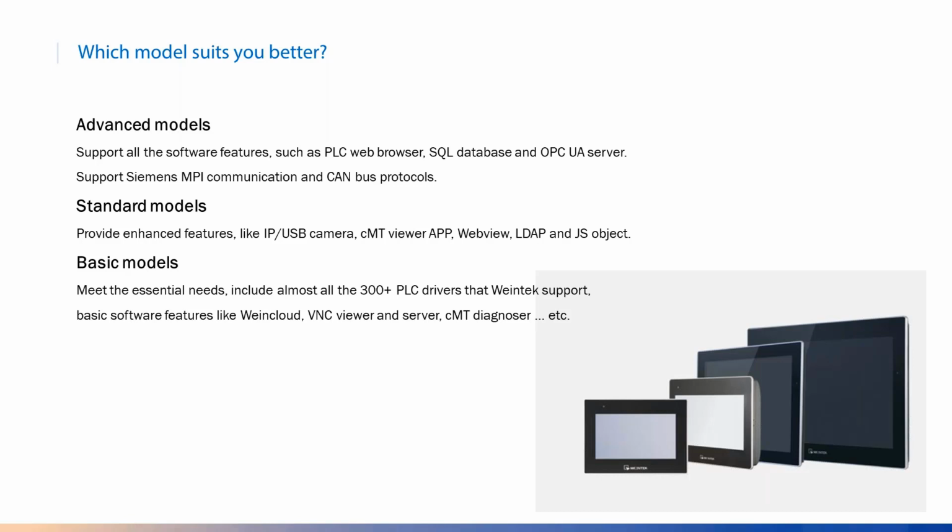As for standard models, it provides enhanced features such as IP camera or USB camera, cMT Viewer, web view, LDAP, and JS object here. For the basic models, it is basically for the essential needs. So it has almost all the PLC drivers we support except for the Siemens MPI communication and CAN bus.